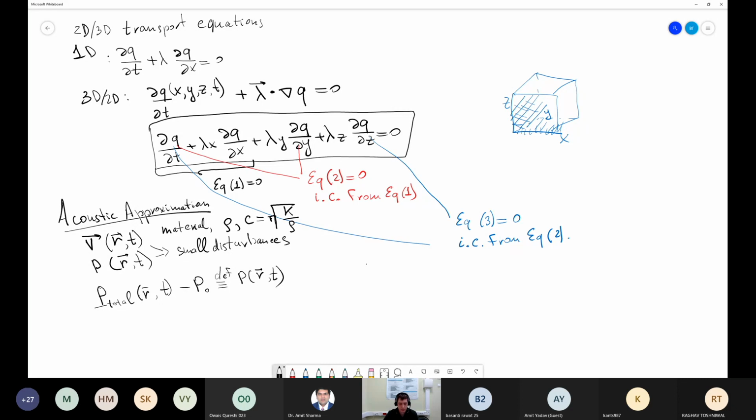And the system will have the view like rho multiplied by the partial derivative of the vector v over the time dt plus gradient of p is equal to 0, or maybe the right side as a source function, like some explosion in the water, the dependence of the external force on the volume of the fluid. And the second equation is d pressure over dt plus rho c squared multiplied by the gradient multiplied scalarly by the vector v is equal to 0.